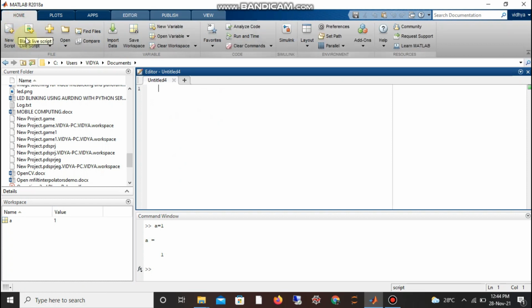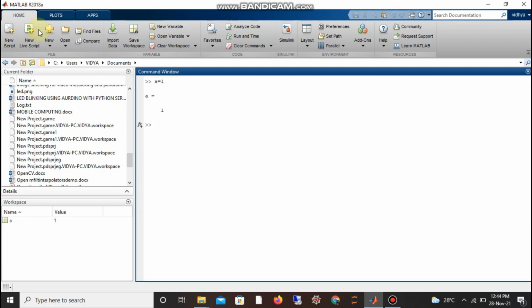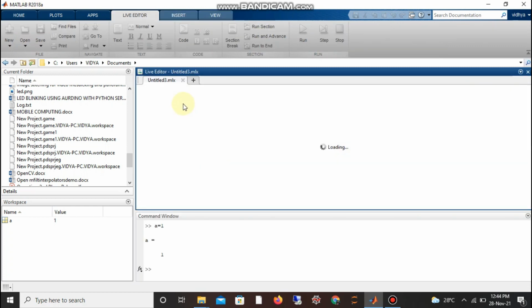Next is live script. You will not find live script in versions below 2015. Live script is nothing but you can write line by line and execute it without waiting to complete the script. For example, closing it, and I'm just clicking the live script. The live script will be untitled.mlx. Just write one line and then execute. This thing I have also covered in my first video. The output will come on this side, not here. Yes, so you can execute line by line.